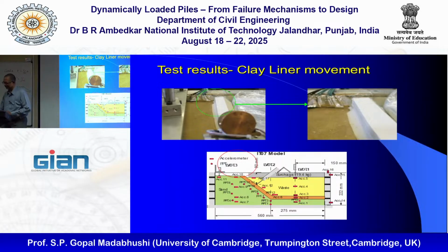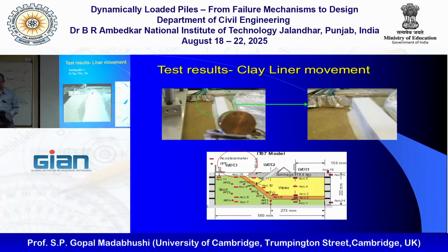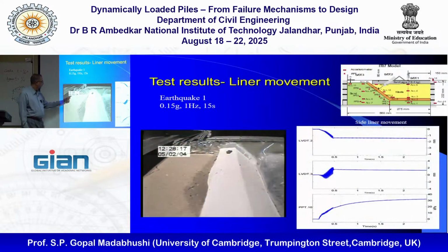So post-test, I mean, this is in-flight picture, obviously. We could see the soil here is now gotten wet because of the pore pressure generated below. The water came up and created these kind of sand boils behind, because we held the water table about here, and so the water coming to the surface means there has been liquefaction.